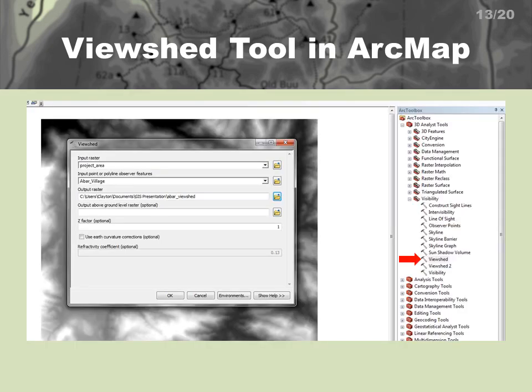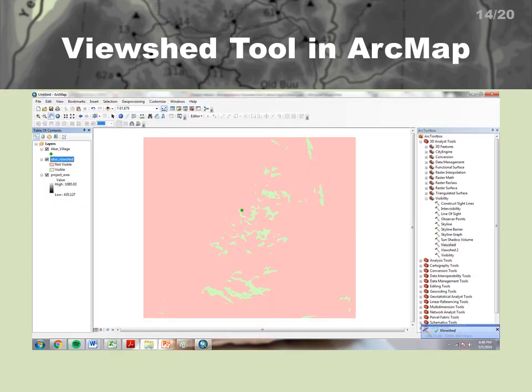Here's the Viewshed tool. Our input raster is our DEM of the Lower Fungom region, and I put in our point. I've also chosen a location where the output file will be saved. I'm leaving the other options how they are. Then I click OK, and after waiting maybe 20 seconds for it to calculate, this is our output.